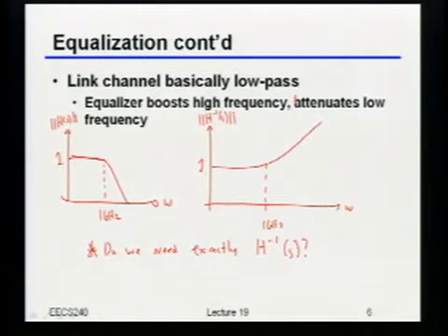Yeah, you made the right motion. Just speak up. H inverse of s is lower than what you actually need. Okay, well, when you say lower, what do you mean? DC gain is less than 1. There we go, right? I can multiply this thing by any arbitrary scale factor. And as long as my SNR is still good enough, that's still perfectly fine, right? I'll still get something that's flat over frequency.